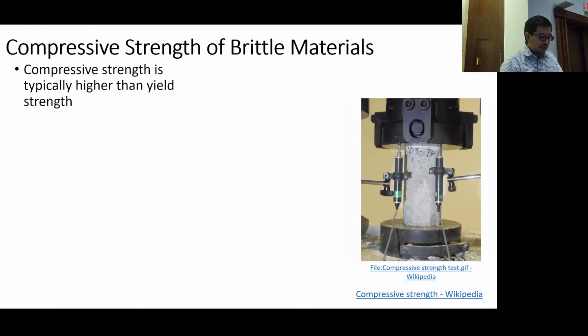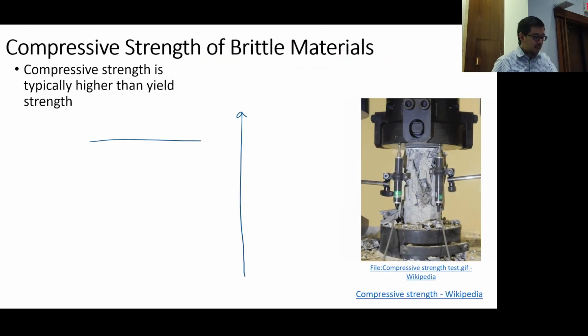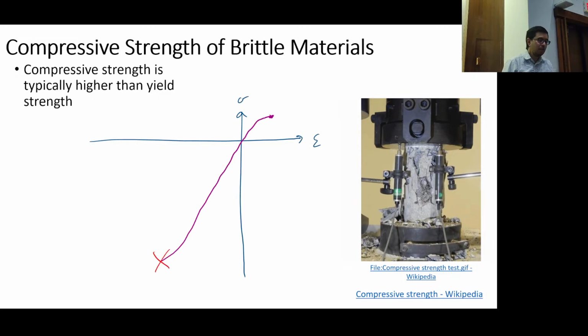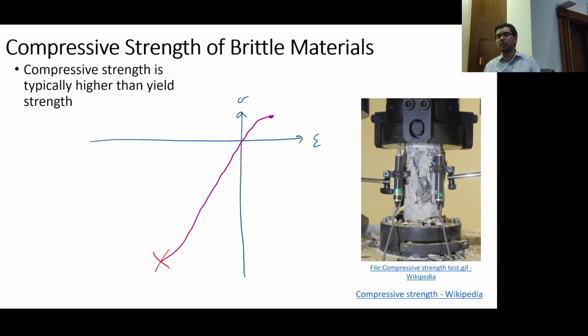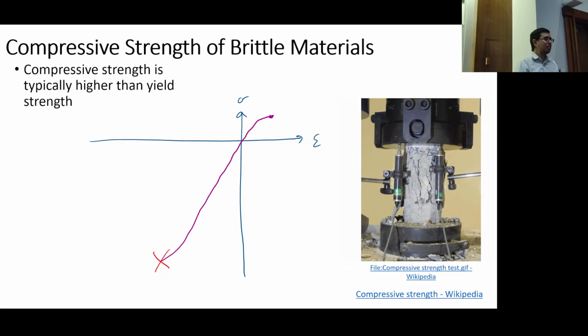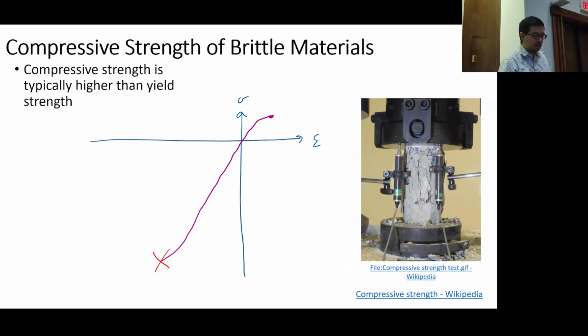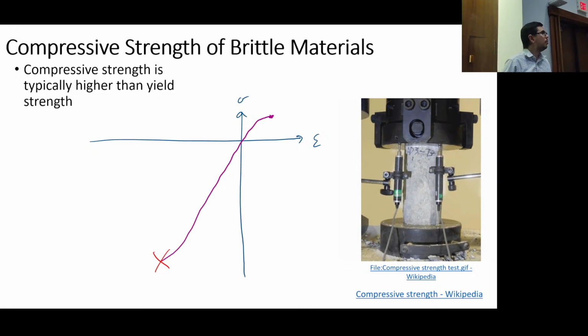Okay, so this is kind of a stress-strain curve for a brittle material, and it doesn't have much of a ductile region, as it doesn't really have much of a yield. Even this kind of turning over behavior, the flattening on the curve, is maybe misleading, okay? But it just catastrophically breaks. And as we've discussed before, the compressive strength is typically higher than the tensile strength.